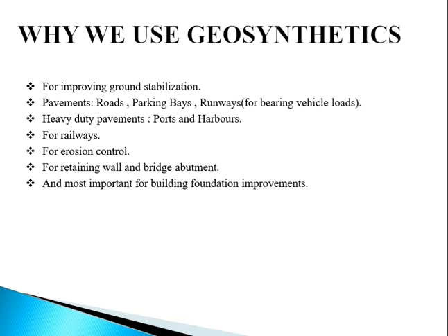So why do we use geosynthetics? We use geosynthetics for the improvement of ground stabilization, pavement for roads, parking bays, runways or for bearing vehicle loads, heavy duty pavements like ports and harbours, for railways also, for erosion control, for retaining walls and bridge abutments, and most important, for building foundation improvements.